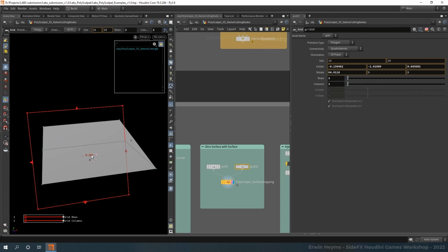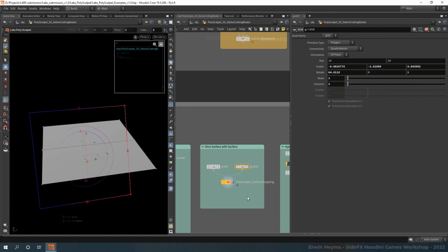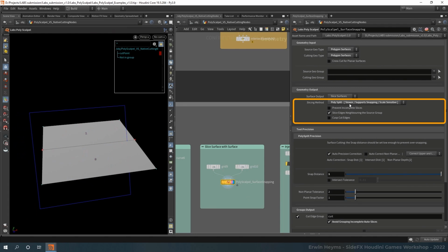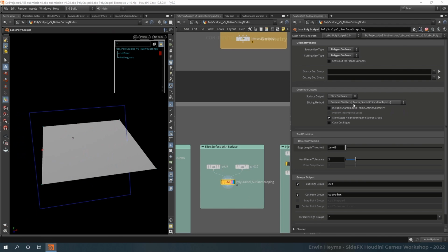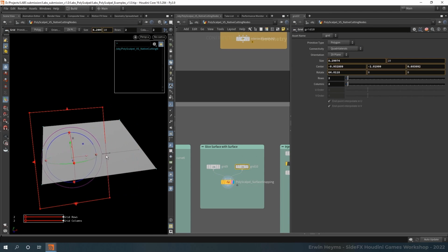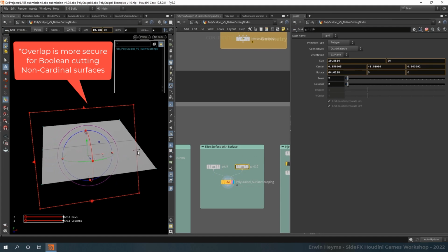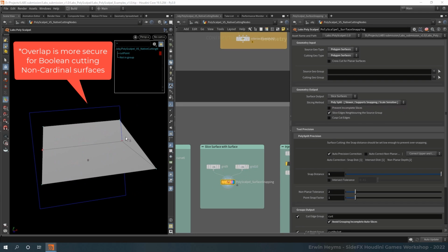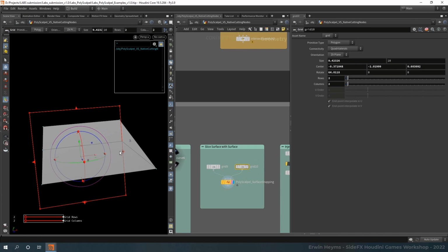Now, this snapping feature is only enabled when we are in polysplit mode. In Boolean mode, which is the other mode of the tool, we don't have this behavior. And in this case, we do need to make a complete cut. In this case, the geometry has to either be exactly on top or overlap. But in polysplit mode, we do have the ability to auto-complete our cuts, even if they are partial. So in this case, you can see that it makes the cut just fine.